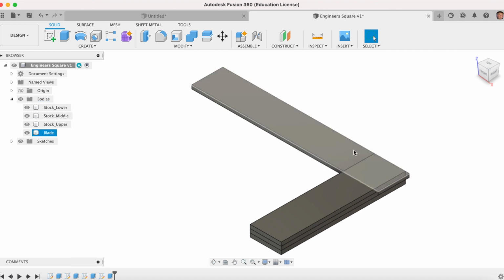All right. What we need to do is put some holes in here. Now, if you look at the drawing, they are 3mm holes, 10mm up, then 30mm spacings, all the way up to the top. I believe the middle one's 84 and 94, I think, from memory. Okay, so let's start on this now.